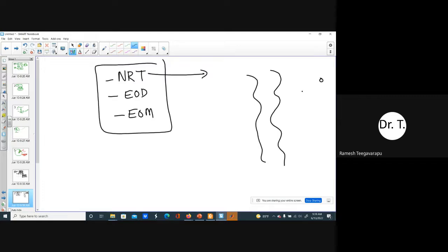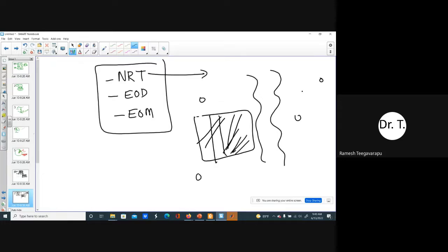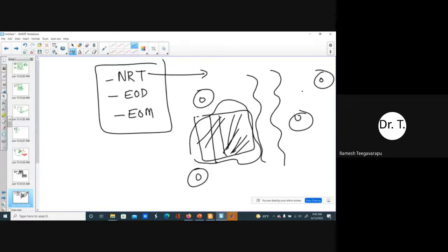And if the rain gauges are further apart like this, then a heavy thunderstorm, which we are prone to, a cell in this area will not be captured by this rain gauge, will not be captured by this rain gauge and this rain gauge. So this is a very localized thunderstorm that might create a tremendous amount of rain, and if it is not registered by the rain gauges, that does not help us in providing warnings, because this canal will be flooded.